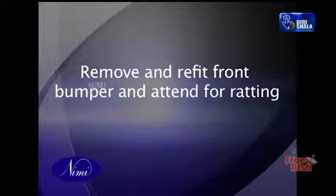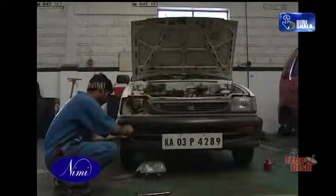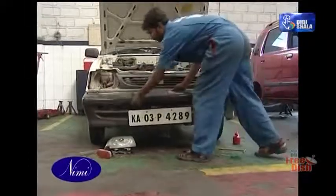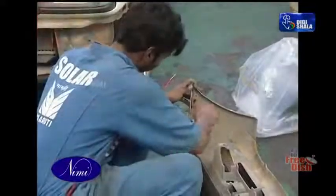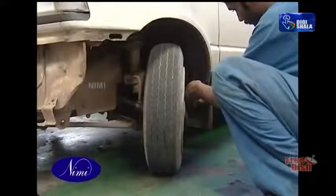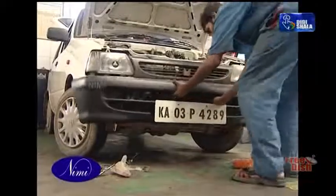Able to remove and refit the front bumper and attend to rating. Remove the headlamp. Remove the bumper mounting bolts to the fender. Remove the wheel guard mounting retainer of the bumper side. Installation is the reverse of removal.